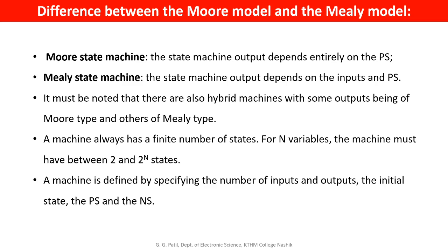The difference between Mealy and Moore sequential machine model: most of the time in examinations this point is asked, differentiate between Mealy and Moore sequential machine. So you should know the basic point of distinction between the Moore state machine and Mealy state machine. That block diagram we have already studied. In the Moore state machine, the output depends entirely on the present state.